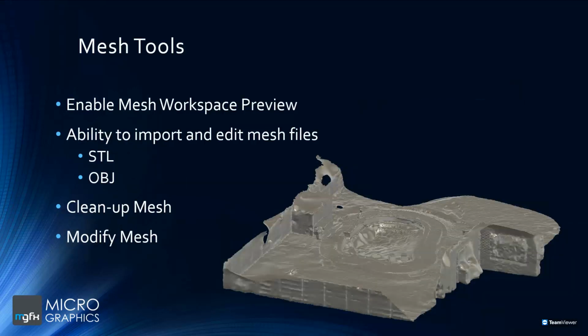So to work with mesh geometry inside of Fusion 360, you will want to enable the mesh workspace. I'll show when I go back into Fusion where you can enable this, but this will give you tools specifically for processing and editing mesh geometry. The reason for needing to enable this is that at the moment it is still a preview function, but it has been around for a few years and will eventually become a fully fledged function within Fusion.